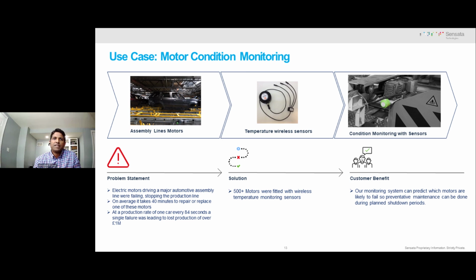In the second phase, we uploaded data from the existing wired sensors fitted to a conveyor track gearbox to the Sensata IQ dashboard, custom designed for this car manufacturer. The acceleration waveform and the velocity RMS calculations were also displayed, and we set alarm limits for the RMS vibration levels as well. So the car manufacturer is now looking at 4 levels of monitoring, depending on how critical the assets are and what immediate budget is available for this predictive maintenance.